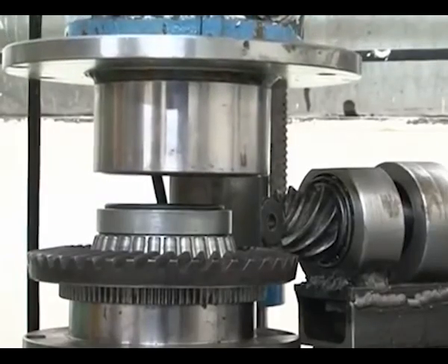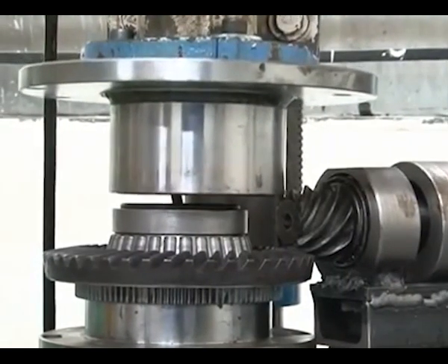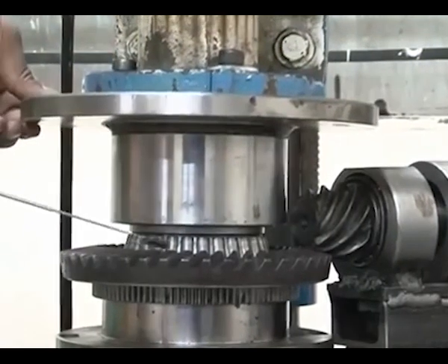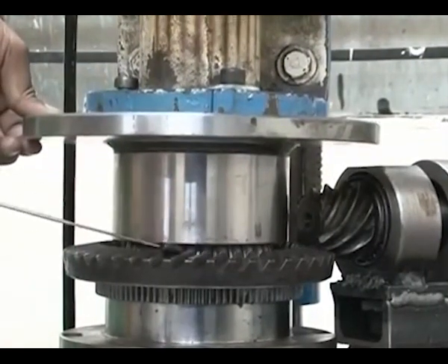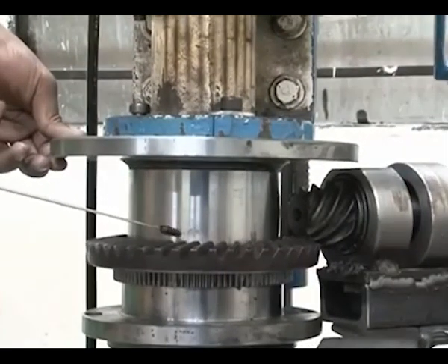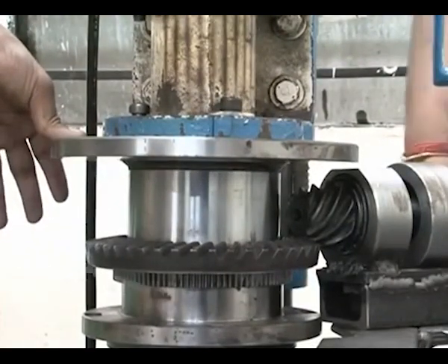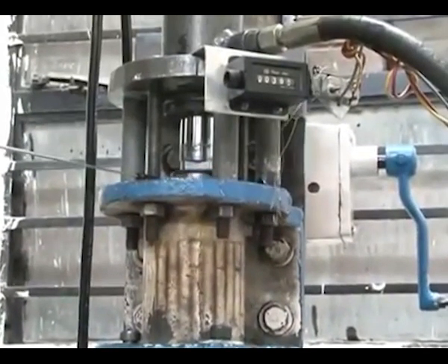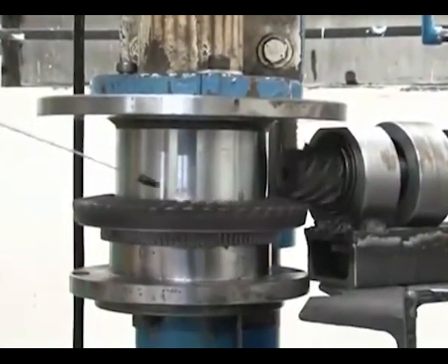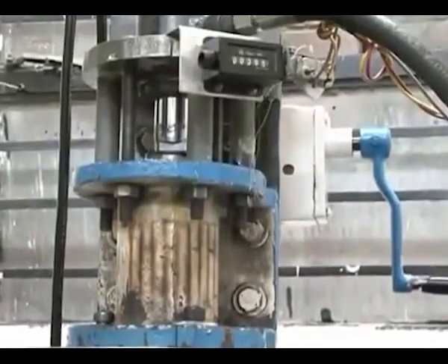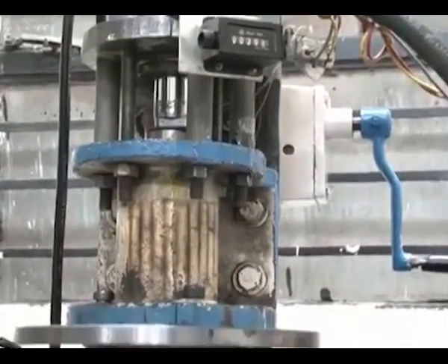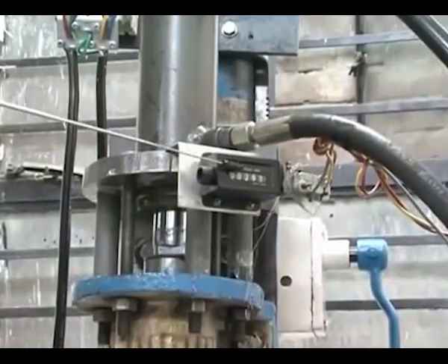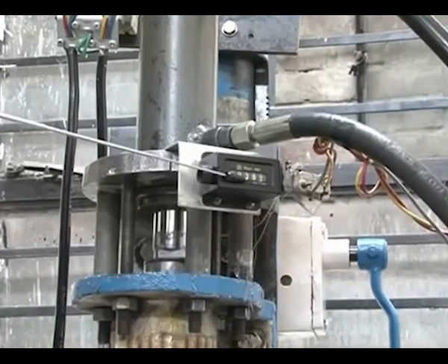Now you can see the complete tooling that is sitting on the rotational tooling. This is the top plate that covers the external rotational tooling, and this is the bottom plate wherein the external tooling is already existing. In this way the complete tooling is mounted. Once both motions are given, reciprocation motion to the medium as well as the rotational motion to the workpiece, this is how the rotational abrasive flow finishing setup runs. The stroke lengths are controlled by the limit switches and the number of cycles is counted in the mechanical counter.